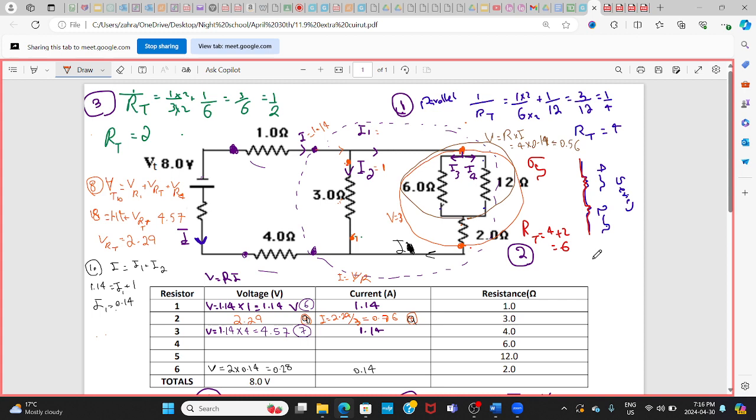Step 8. Look at this battery providing the voltage. Across the battery there is a voltage, and this voltage provides the power. So the voltage across the battery is equivalent to the addition of all of the voltages that you see here, since they are connected in series. So the voltage across the 1 ohm, plus the voltage here, because these three are connected in parallel.